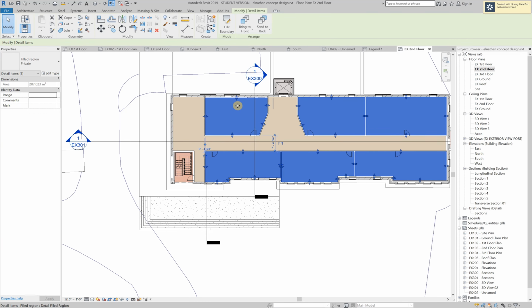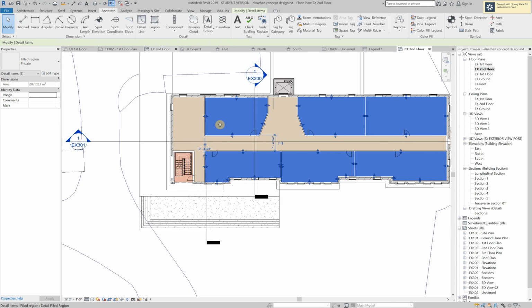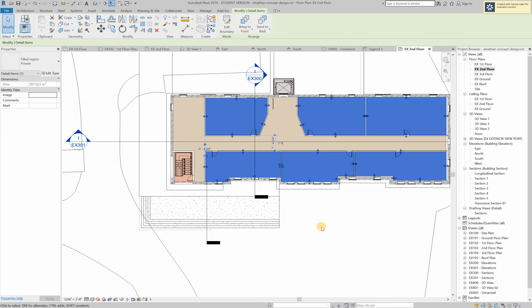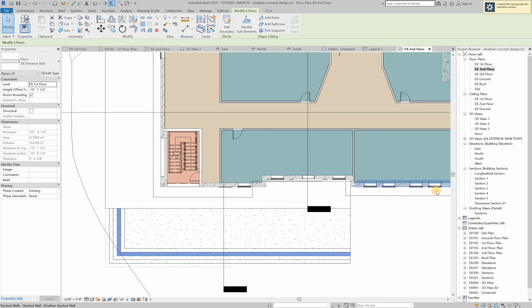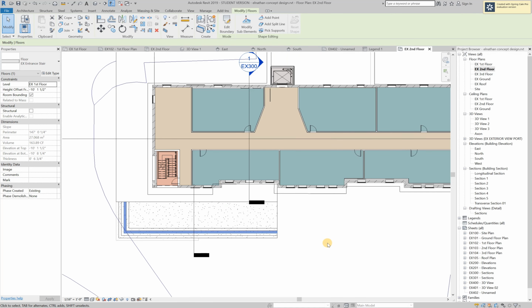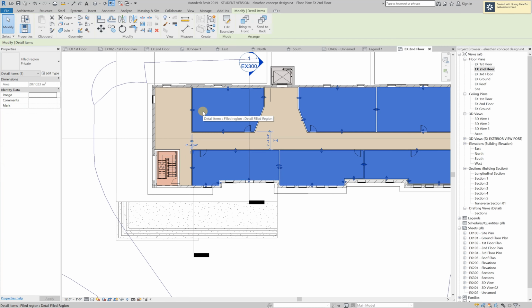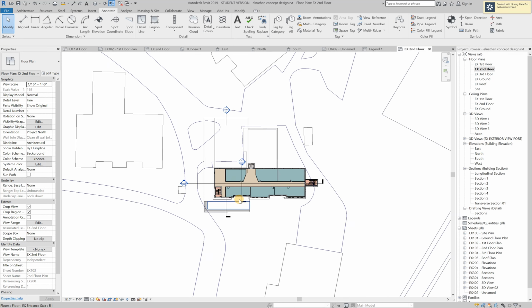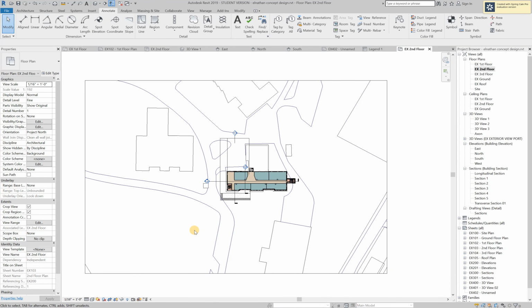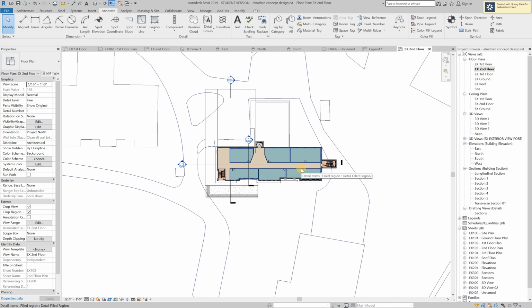Even though it is BIM, I can add regions. And a fill region is under annotate. There it is. This is a 2D construct. That's the best thing about Revit for me, is that you can model things in 3D and also layer 2D line work or filled regions. That way, if you need to quickly represent something, instead of taking like 30 minutes to model it, you can just draw a couple of lines and there you go.